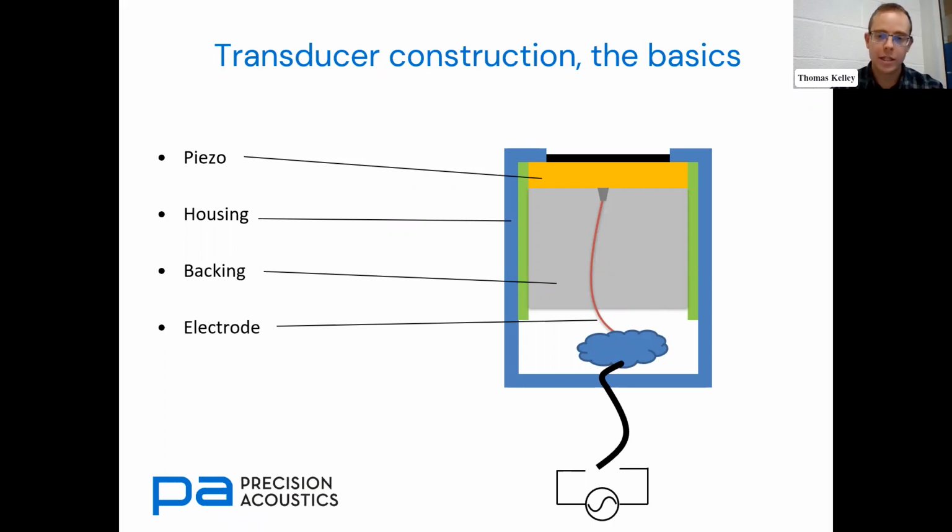Of course, this relies on having a housing that's made from something conductive. So if you're going to use something else like a plastic housing, then you're going to need to get an electrical connection to the front some other way. So it could be another soldered connection, or maybe a wraparound tab on the piezo ceramic element if you're using piezo ceramic, and another solder joint that way. So something to think about.